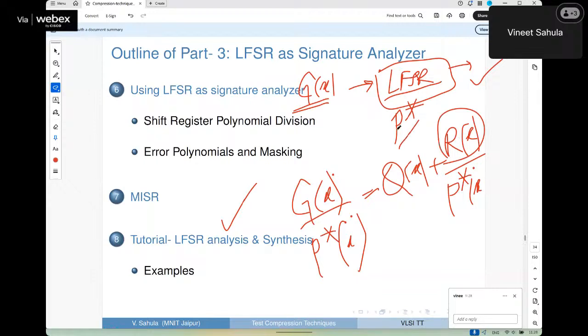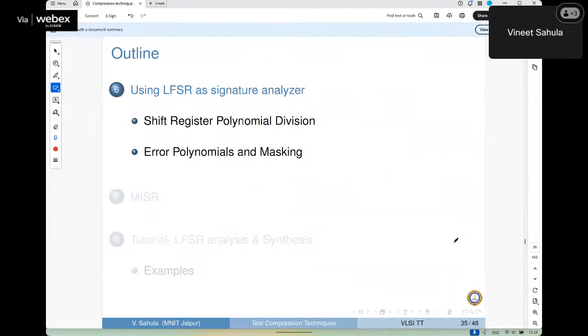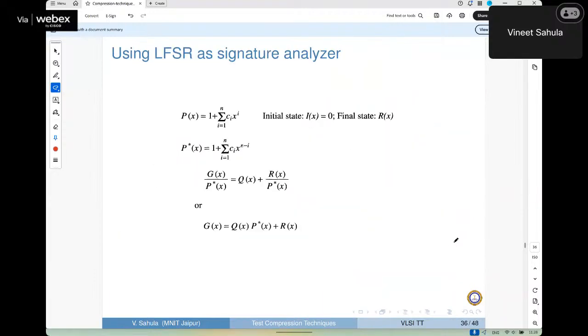We are taking P star because we take the first bit as MSB. So the first point is not AM, it is A0 or AM something. It's a reverse polynomial, P star. The choice is because in the complete sequence, my first bit is MSB. If my MSB comes later, I will choose P only here. Right? So I'll take just one example and close. That's all.